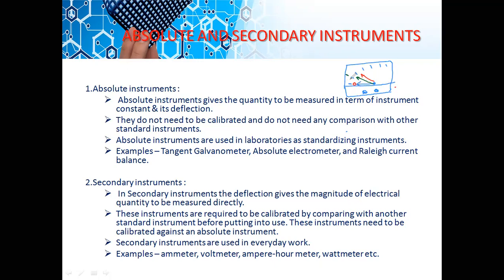We are trying to give values to this scale, according to how the pointer is deflecting. This process is what we call calibration. Knowing the true values of the input quantity, we compare the values and how the pointer deflects, and then we mark the point of deflection as the true value. This procedure is what we call calibration of the meters.